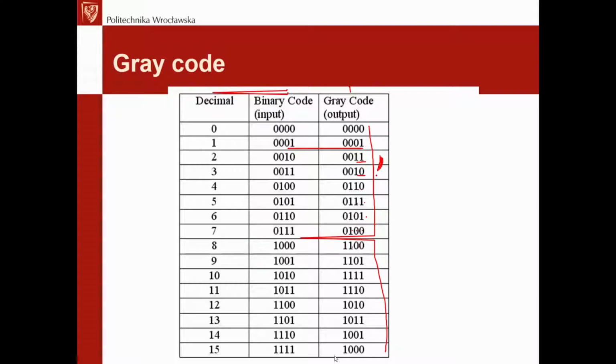If some device is delivering its states, and we know that the states must differ by only one position because they are successive states, then besides the reduction of the required detector frequency, it gives us the chance to check transmission errors from various EMI noise problems, because we have a direct control of what shall be available and what we get on our inputs.